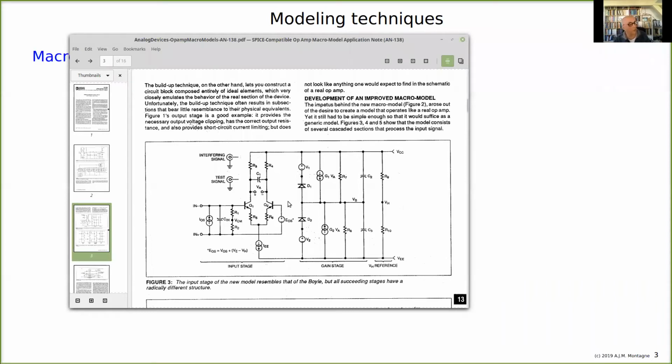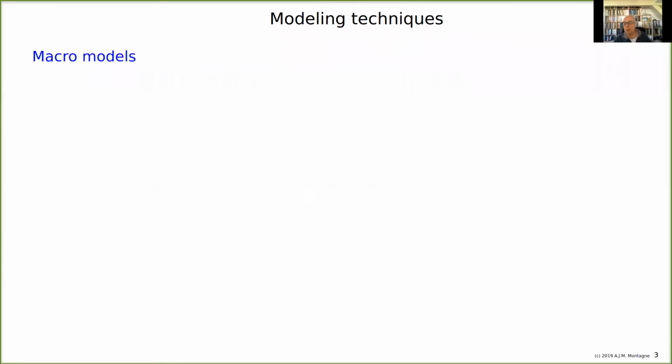For example, here you see in this model the voltage offset, the error. Usually you want to have 0 volt at the input giving you 0 volt at the output, but of course there is an error due to technological limitations, and there can be an offset. But the offset is modeled as a fixed source, while it is some kind of random error that remains after you have tried to make it 0. So that's a little bit the danger of using macro models, and what we often want to use is